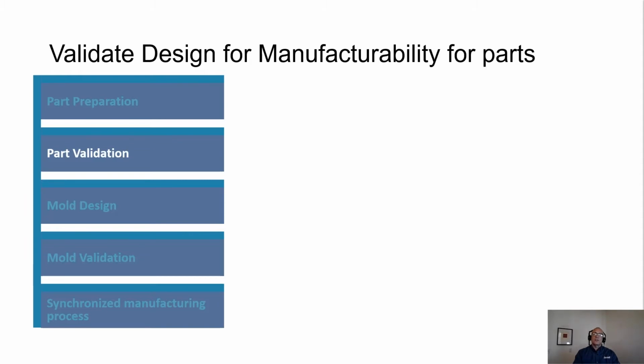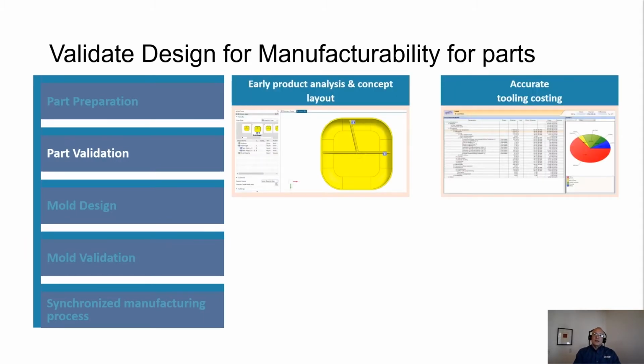It's going to allow you to check for molding issues with your flow, packing, cooling, warpage before any expensive parts are actually made. So that's a bonus there. Second, you're going to keep the tooling cost on track because you're going to be able to see that up front. You're not going to make any last minute mistakes or surprises that may happen.